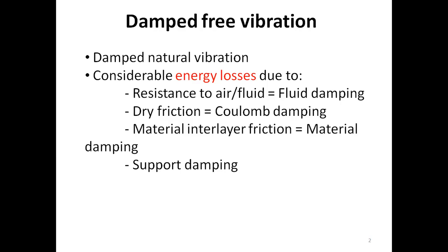So generally we would have viscous fluid damping, Coulomb damping, material damping, and support damping inside the vibratory system. Whenever this damping is considerable, we have to consider it and model our system as a damped system. Next, what we would be discussing is the damped free vibration. From now on, we would include the damping, or energy losses, in the system.